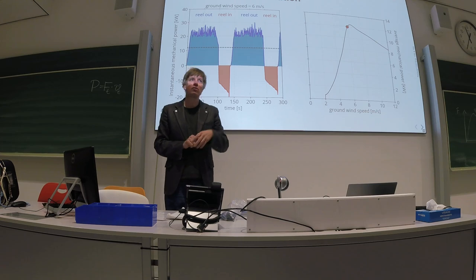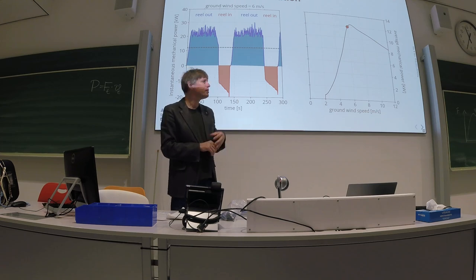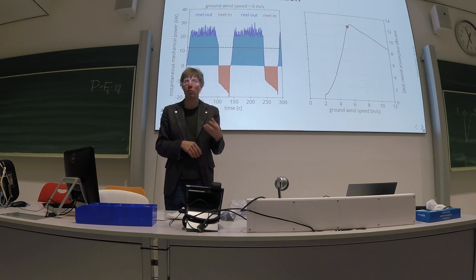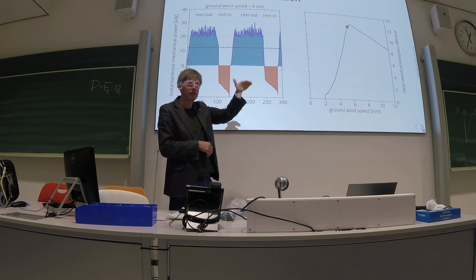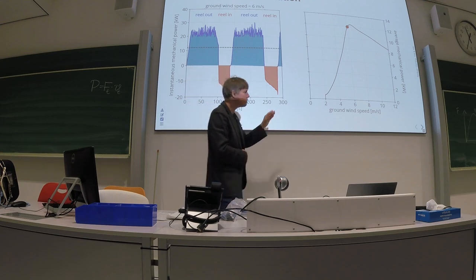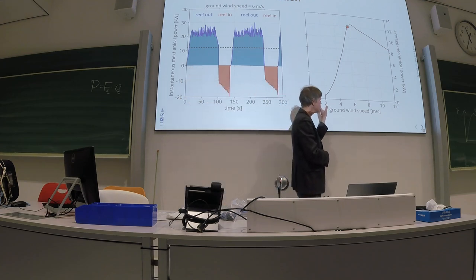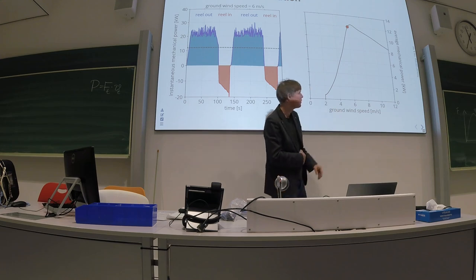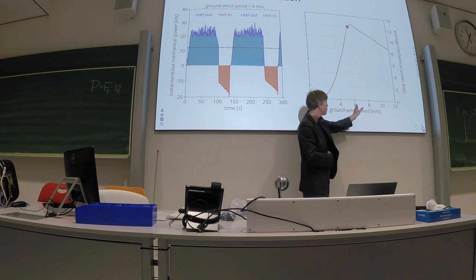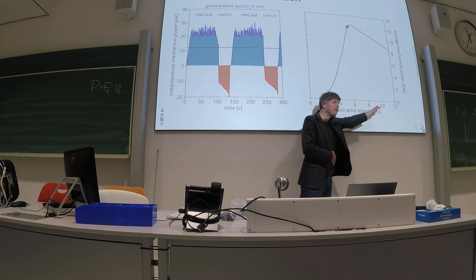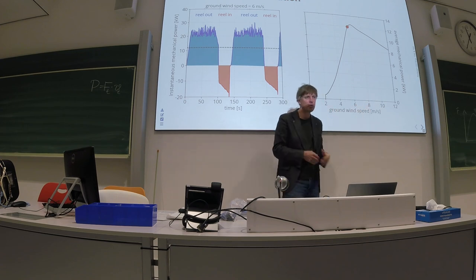But nowadays, to be comparable with turbines that measure at hub height, we also go to our hub height, which is the mean flight altitude of the kite. So typically, when this is wind speed at altitude, you see higher values, because the wind speed at the ground of 6 meters per second at higher altitude is often more than 10. So this whole diagram shifts a little bit.